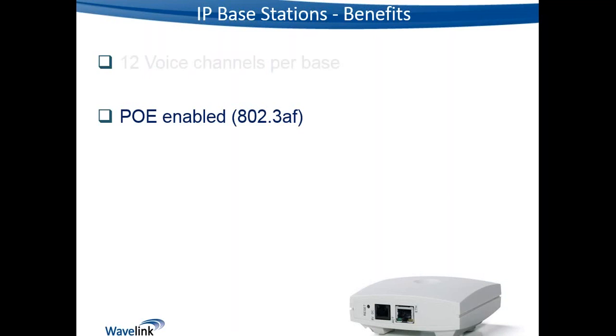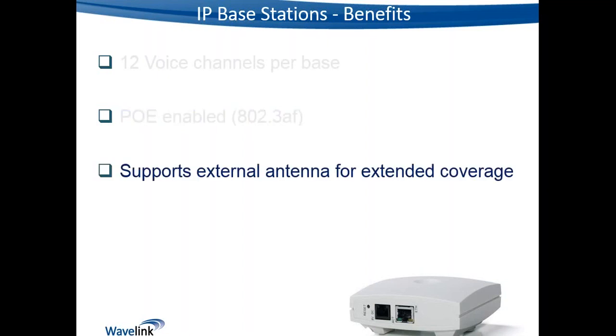We can run these off PoE switching infrastructure. These days it's very common for organisations to have deployed PoE switching, or power over Ethernet switching, which can not only provide the communications to the devices hooked up to that switch, but also power those devices. So the original PoE standard 802.3af is compliant with the Spectralink IP bases, and anyone who has a compatible PoE switch, which will be just about any PoE switch will support af, it's the original standard, and the lower power of the two standards, will be able to run IP base stations.